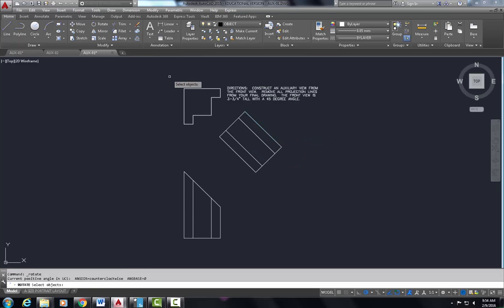So as I look at my object again, I'm going to rotate it so I can kind of visualize it. This line right here is this little line here. It needs trimmed up and modified. And this line right here is this line right here. To get my lines that travel from front to back, I project those out of my front view up in. And I'm going to project those all the way across because I don't remember a whole lot of where they belong right now.